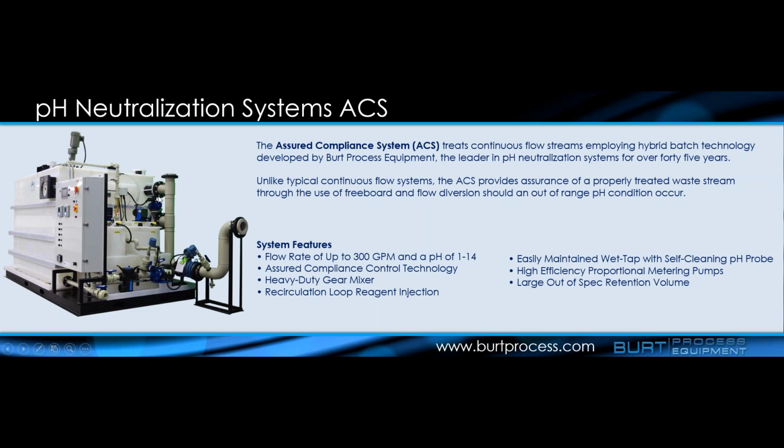So if you had to, you can go into a batch mode where this additional tank volume could fill up for treatment. That's standard on an ACS style system. When more than that volume is required, and that volume is usually 3 to 5 minutes of additional residence time, which doesn't seem like a lot, but it really is a 20% increase. That can be enough to get you into compliance.